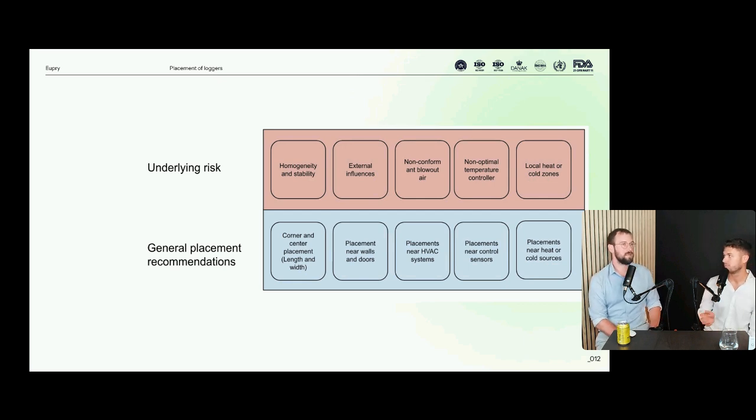Oh, that's a really good question. Again, I would say, what are some of the risks that are posed to this fridge? So the whole rationale behind choosing summer and winter mapping is that the external influences will be so large that they will be reflected on the temperatures of the products inside the temperature controlled unit. So I would say, as a rule of thumb, again, I'm against rules of thumb here, fridges are normally resilient to temperature changes of something like 10 degrees Celsius. We have customers from all around the world, 10 Kelvin.